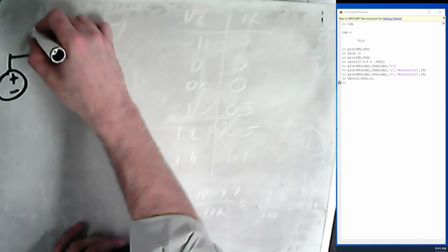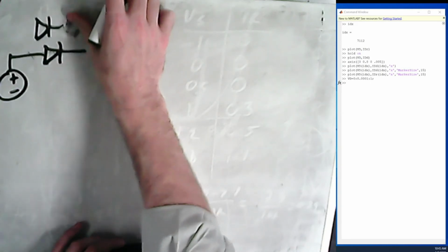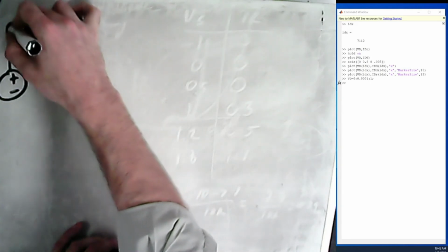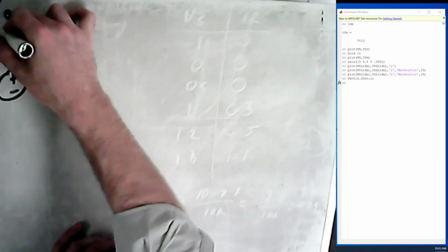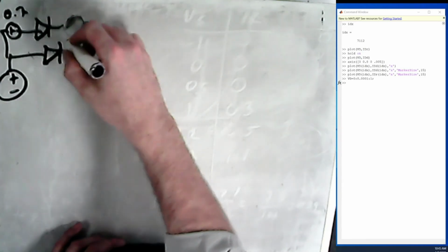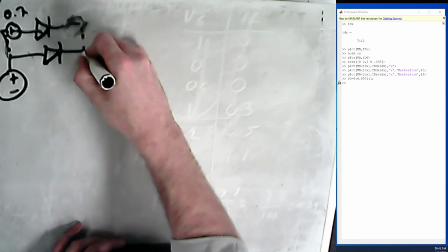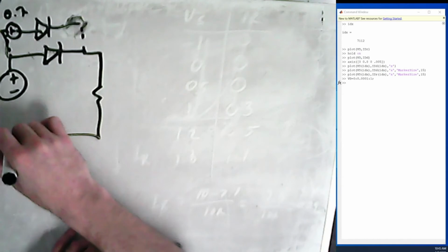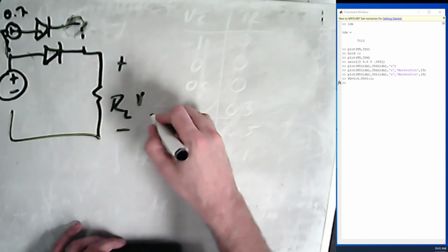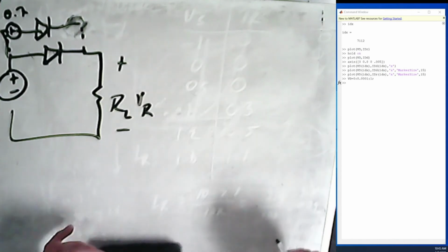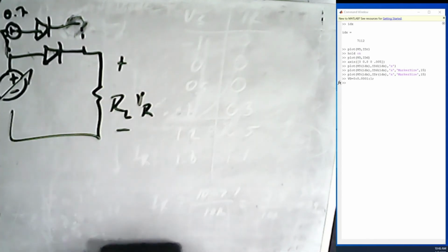There's our diode. We're going to replace this, remember, in our minds with this, and I'm actually going to put in the voltage source here, 0.7, so we can just add these directly together. So remember, this is kind of replacing that one. We have our R load, and we're measuring this voltage of our R. And we're just going to put in variable values for VS.